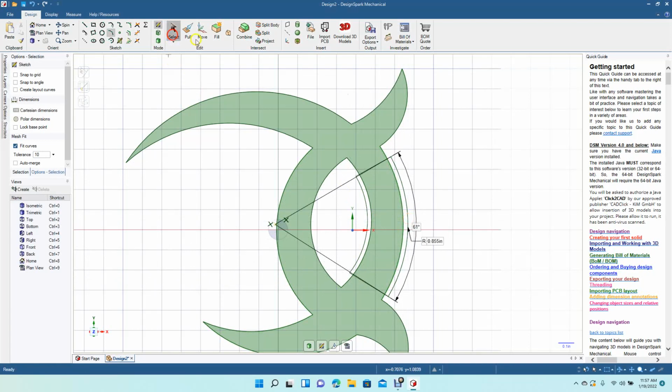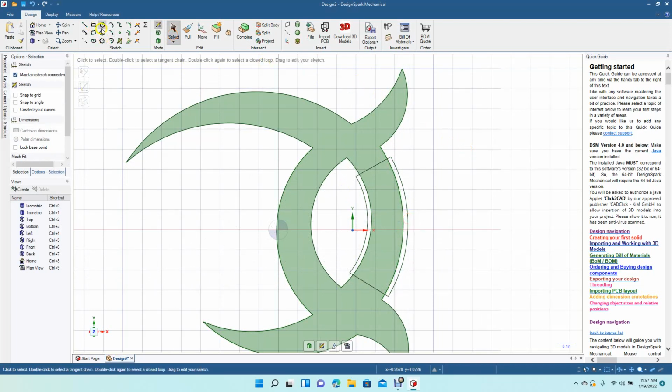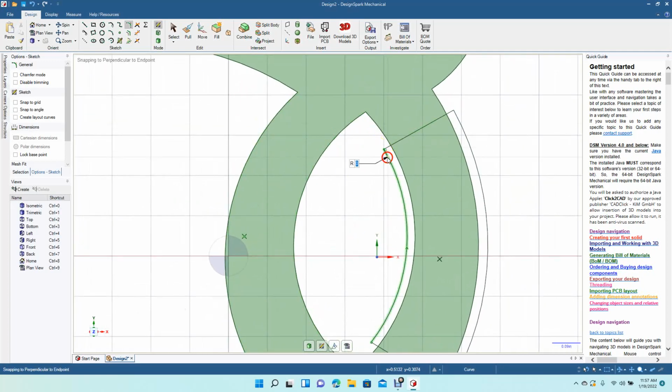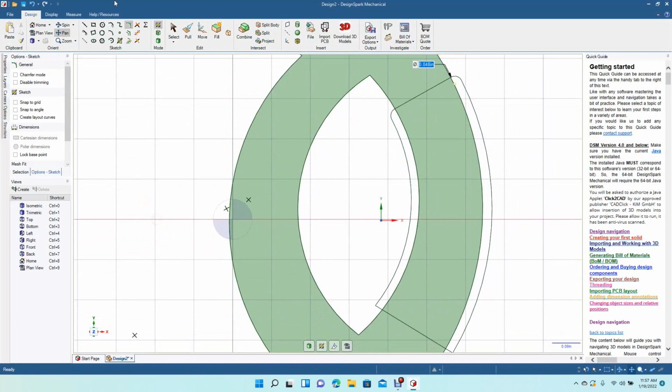Okay. Let's go ahead and spin this. Actually, let's add some radius corners to the handle. So go Control plus. We're going to click there. 0.024. Let's pan up. Do the same on the bottom.